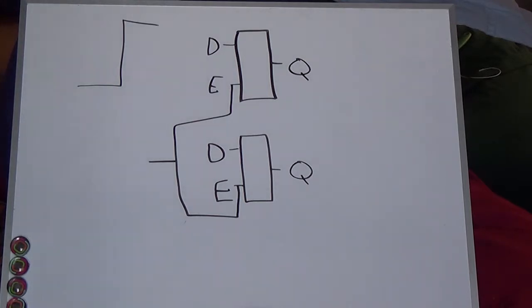The only thing is, if I pulse enable high at the same time I send a signal for other logic gates to release the signal to this data, you could see there might be a problem. Enable might be triggered before the data gets to the input of these positive edge triggered D flip-flops. And that would cause a pretty big problem. It would stop the operation of the computer. It wouldn't function properly because the registers wouldn't be receiving the proper data.